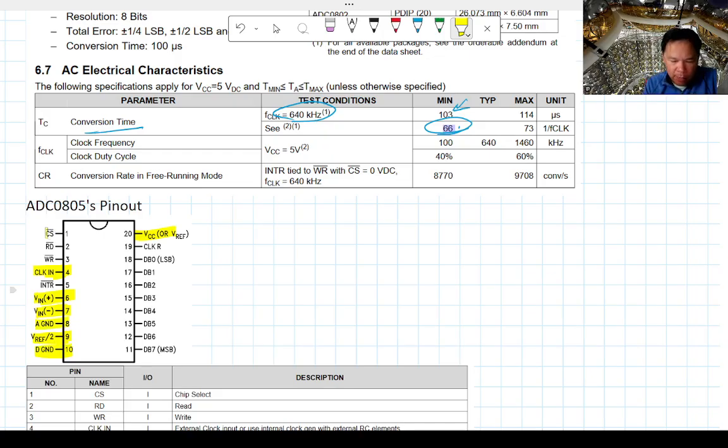Okay. This is the ready, and this is the conversion start, but these are always flipped logic. So if you want things to be ready, the ready bar, you actually have to be 0. So when something is ready, you actually want to send 0 there, and that way you flip that logic to 1, so now it's ready to convert, or to read or write to your ADC. So that's the extra clock cycles that get built into it. That's why it gets blown up to 66 clock cycles.